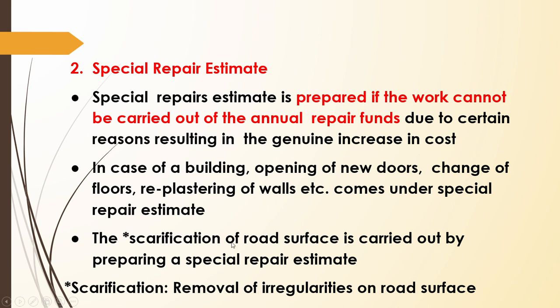The scarification of road surface is carried out by preparing a special repair estimate. Scarification means, if the road is not good, then we have to clear the road so that it can be rebuilt or repaired. Okay, maintenance has to be done. So that particular process is known as scarification. It comes under a special repair estimate. The cost incurred is higher, but we have to get it done. So we will prepare a special repair estimate for that.